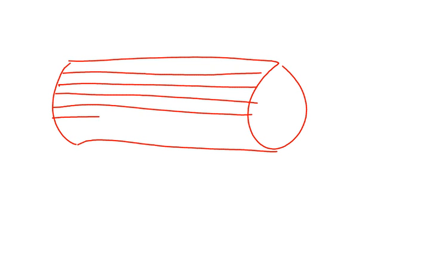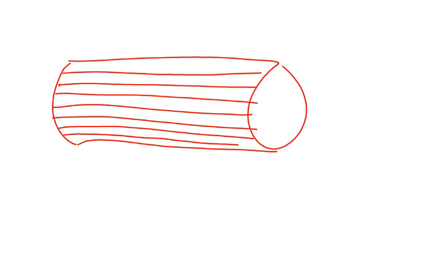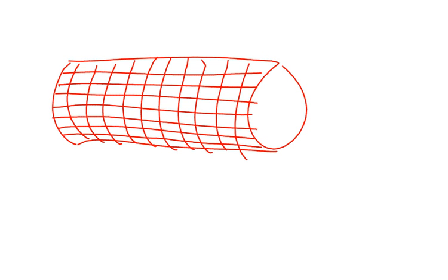And using squares is basically the best way of trying to determine what sort of stress and strain your structure is going to be under. So you draw this grid of squares, and then you go ahead and apply your torque. Then you look at your squares, and you ask yourself how those squares deform, right?